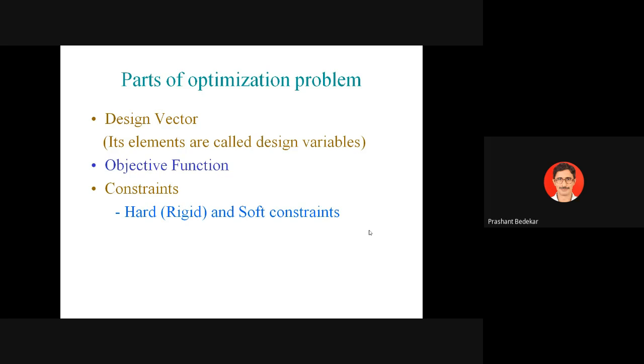But then what about frequency? I have to design the motor for 50 hertz. Once the design is completed, we have to do the calculations and check whether the input given is satisfied with this design or not. When we see that no, this is working properly on 52 hertz, we will reject that design. 52 hertz will not do, because the frequency constraint is a hard, rigid constraint. 50 means 50. Voltage is soft. Okay, 440 volts will do, 445 will do, 435 will do, no problem. So that is hard and soft constraint.